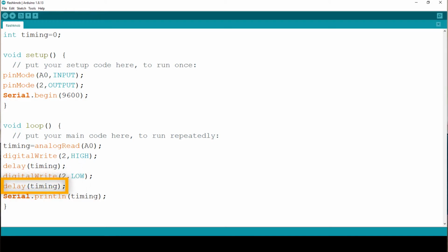In line 16, we have yet another delay, making it hold its off state for a bit. Then in line 17, we have a Serial.println method. This prints to the serial, and it works the same way as it would in Java. Serial.println prints to the serial, then creates a new line. This is different to Serial.print, which does not make a new line and prints everything on one line. As a parameter, we would usually just enter a string. However, this will convert numbers to text, so we can just throw the timing variable straight in, and it'll print it out perfectly. This will allow us to monitor the timing for bug fixing purposes.